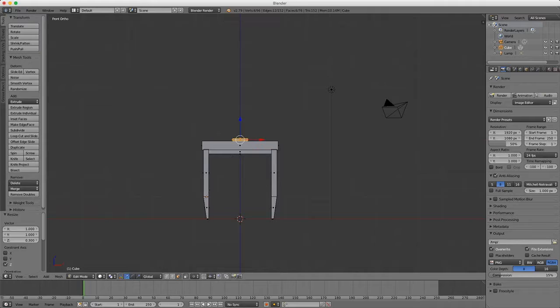Press Enter. Press G, X, -1.35, to move the selection 1.35 units to the left along the x-axis. This will serve as one of 5 wood planks for the tabletop. Press Enter. To duplicate the plank, press Shift, D. Then, press X, 0.7, to move the selection 0.7 units to the right along the x-axis. Press Enter. There is currently enough space for 3 more planks. Repeat this process of duplicating, Shift, D, and moving the plank, X, 0.7, for the remaining 3 wood planks.